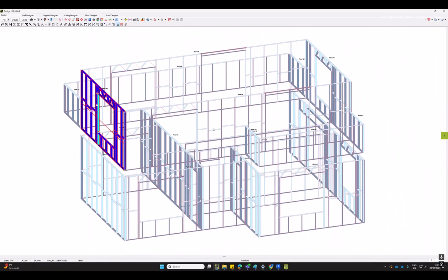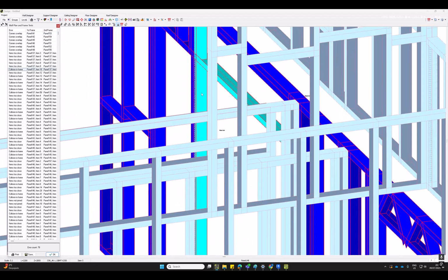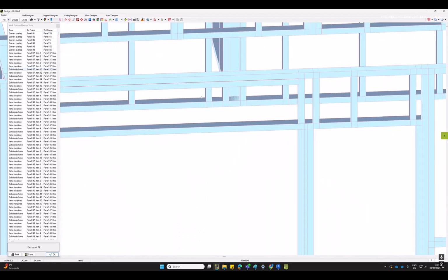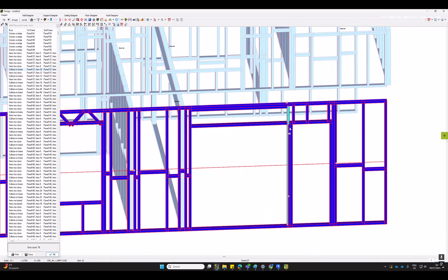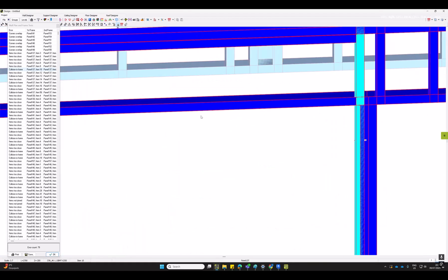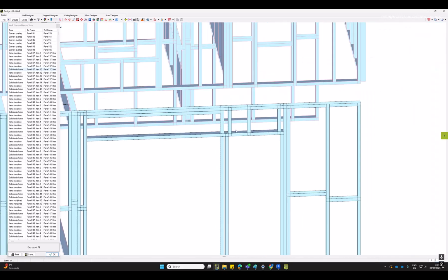The first thing you want to do is to check the collision test to make sure that all the items are adequate to be sent into production. If you find issues like collisions in frame, you can then go back into Revit, Greatech, Strucsoft, and do the changes, or you can adapt those changes in here. Let's say I unblock this and delete that member, and we're good to go.